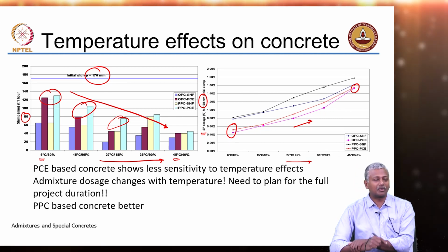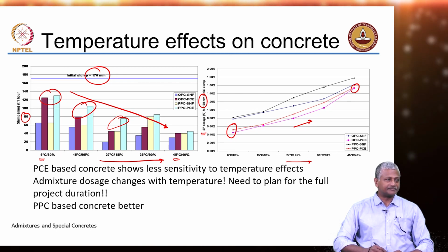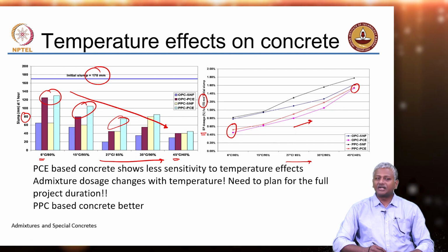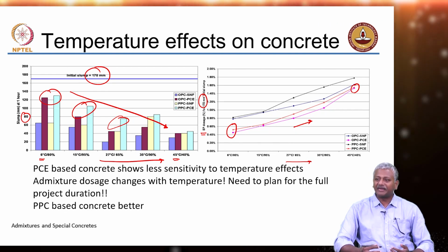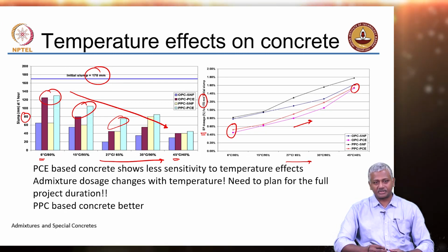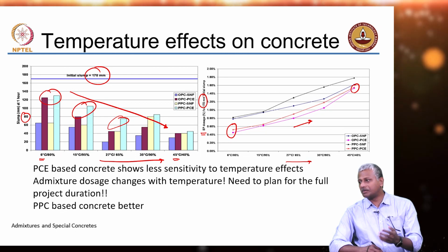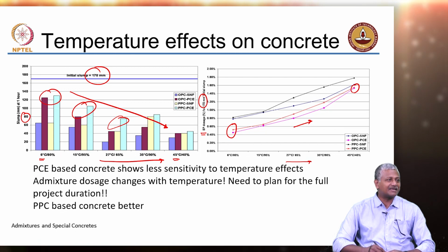So, all of this, what does this go to show you? What does this tell you? It tells you that the planning for concreting has to be done well in advance of the start of the construction project. I come back to the same point. In most of our construction projects, concrete mix design is sought the day before concreting is to be done on site. That is the reality.